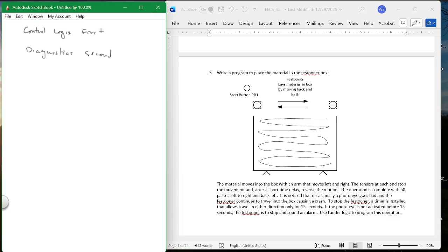Now, you have a choice. You have to use a counter or a number. You can use a counter or you can increment a number in a holding location. Either way works, and I really don't care, but I like counters because they automatically count on a leading edge. You don't have to do a one shot first. So again, you push a button to start.